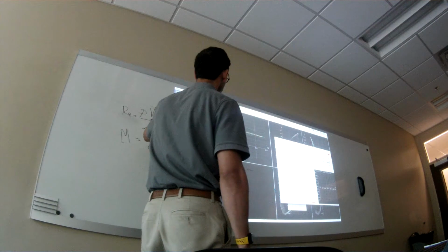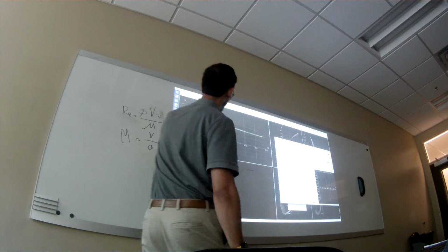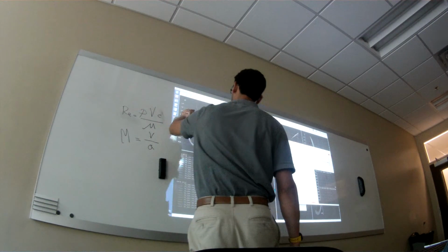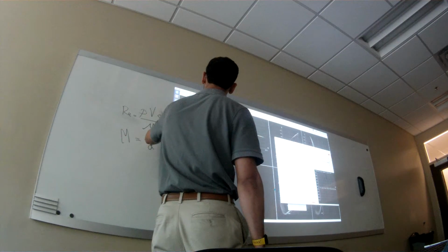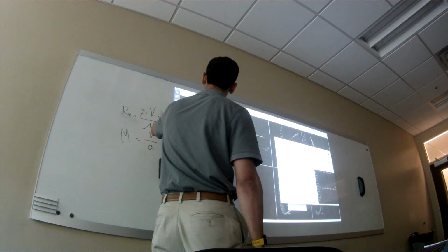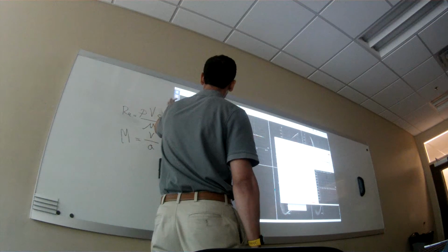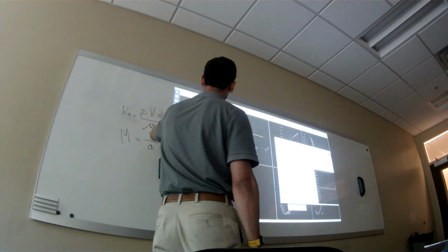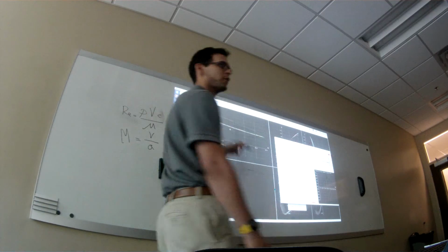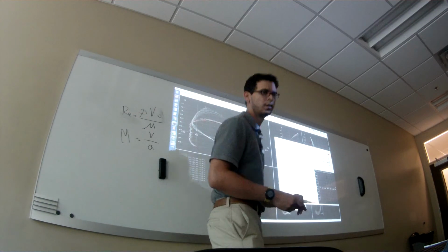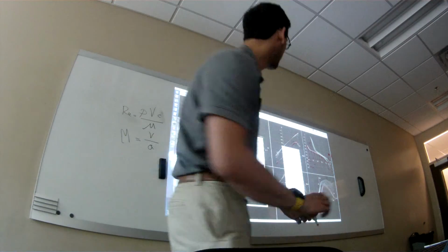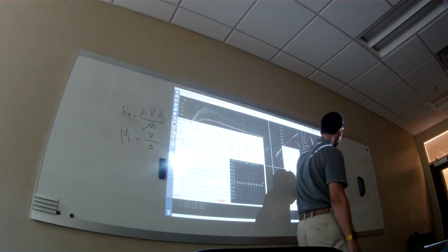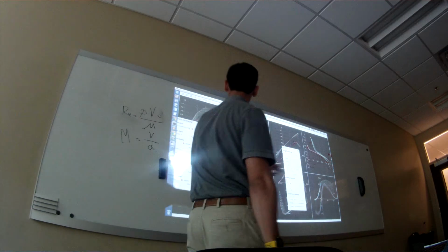So you can see, here's for the 0012. It's a pretty nice bucket, right? But it basically means if I increase lift more and more, sooner or later you're going to stall, and you're not going to get very much lift, but you're also going to diverge and get a ton of drag, which is why your lift to drag ratio, which is down here, peaks and then drops down. If you look at that, that's like what, 5 degrees?